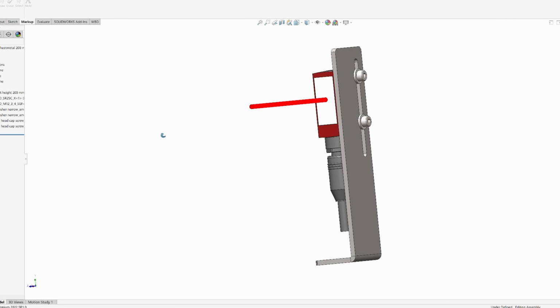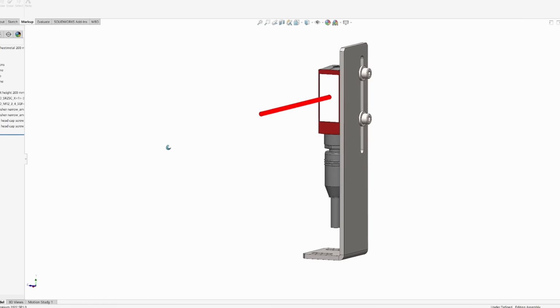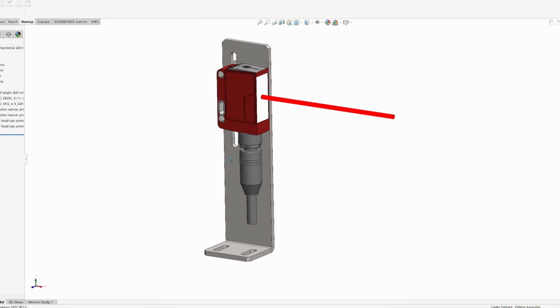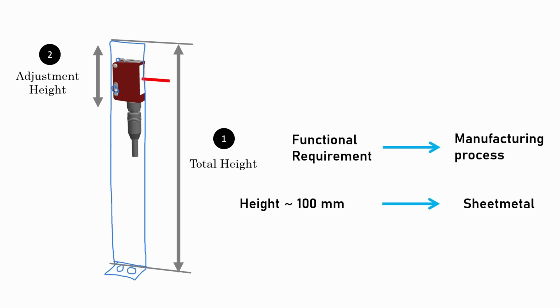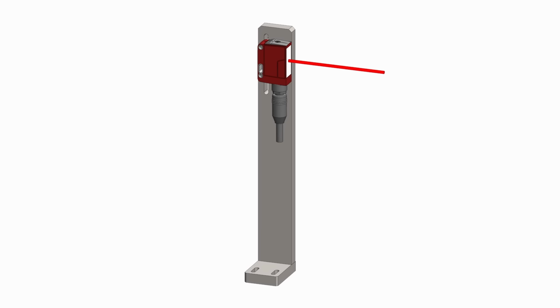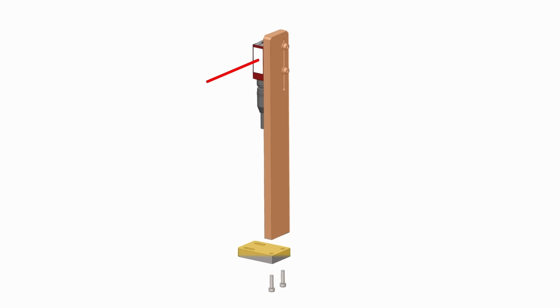With 2 or 3 millimeter thickness of sheet, it is easy to manufacture and very economical. But if the bracket height is going to be more than 200-300 millimeter, you should already decide to go with machining, and then you design the part accordingly.